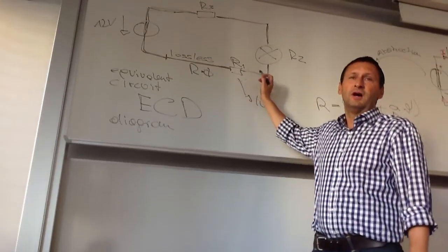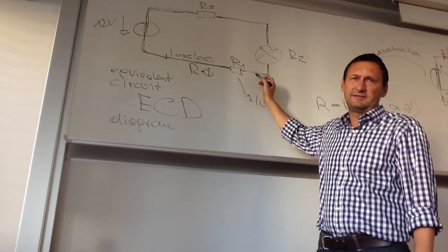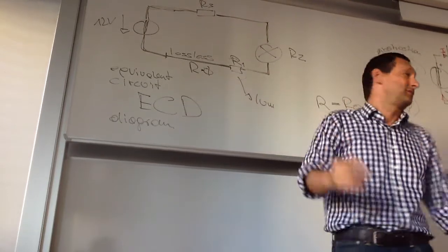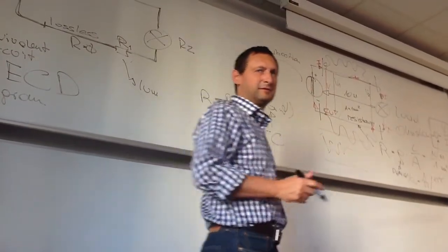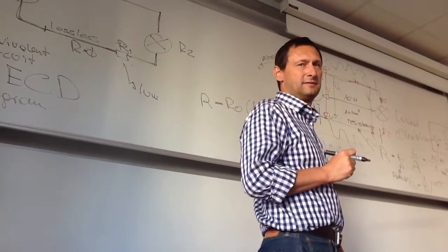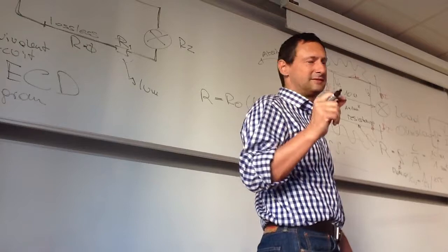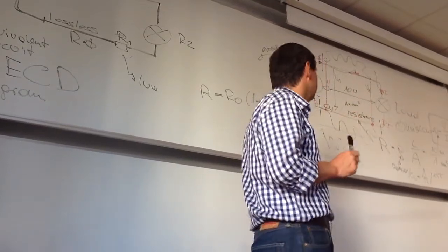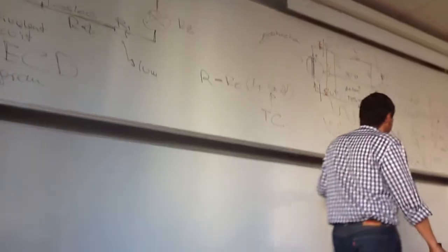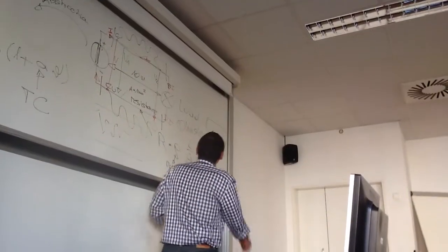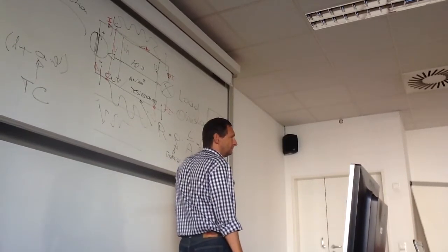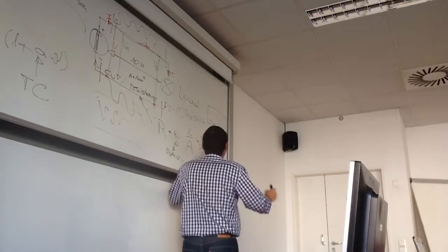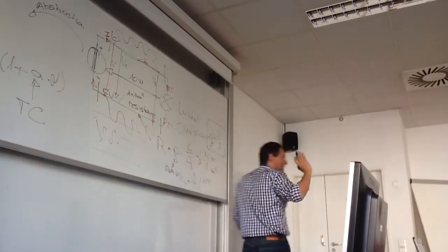For practical electronics, you normally do not account for the resistance of the wires. This is only for this special example. If you're building a circuit on a circuit board, you don't care about the resistance of the wires, because it's so small compared to the other resistances in your circuit. So if you want to calculate the resistance of the wire when we don't have the information of the voltage and the current, we use that formula. You don't need the information about voltage and current.